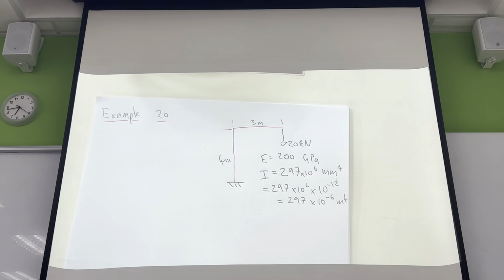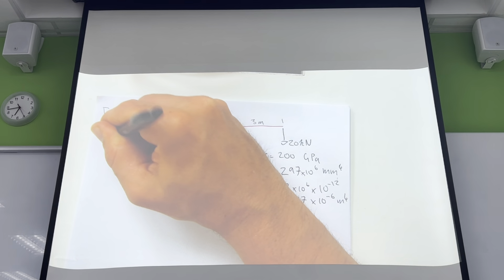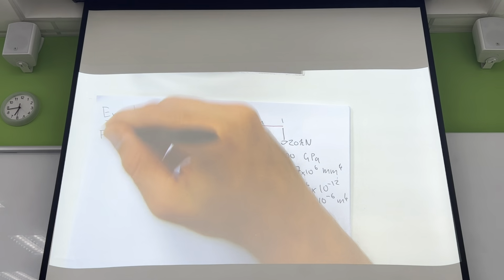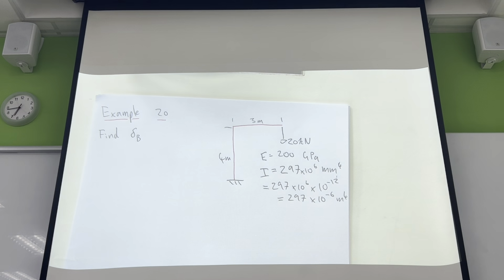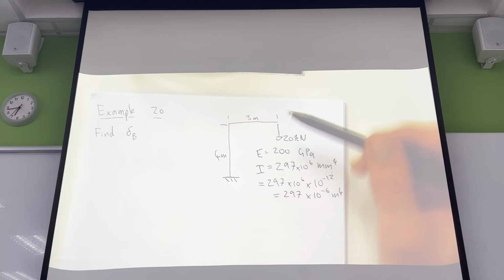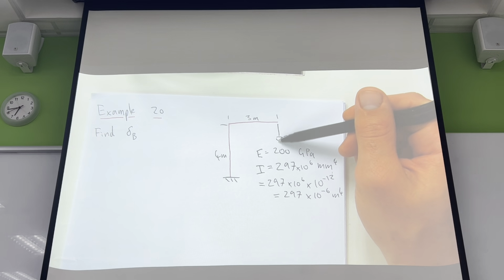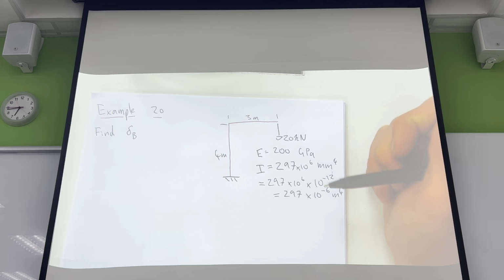And what we're wanting to do here is to find the deflection delta. I'm going to give it some delta at B. Now, the key thing here is that because we're looking at the energy being input by this force, you can only look at the deflection in that same direction, the deflection that is generating work.